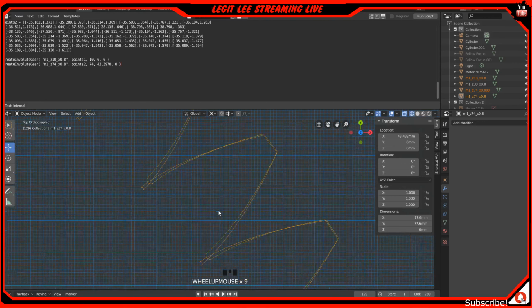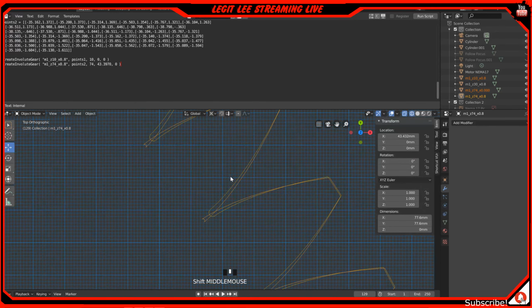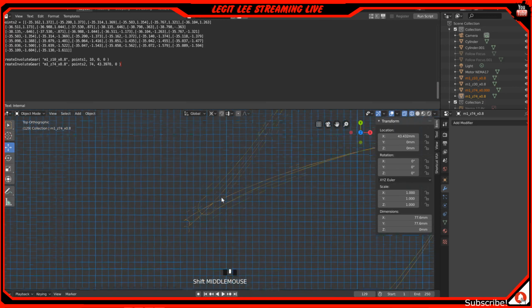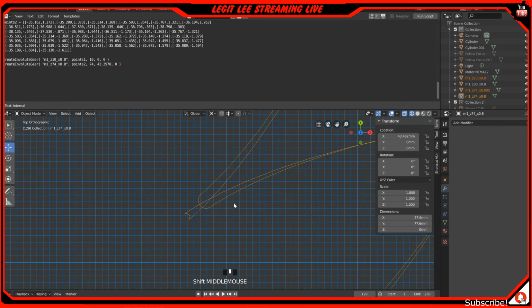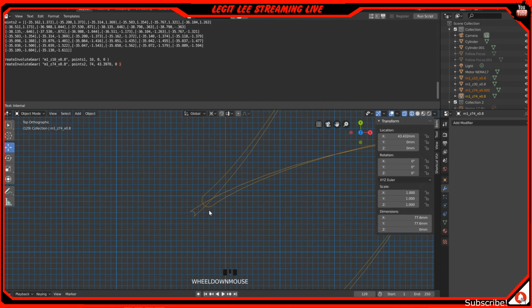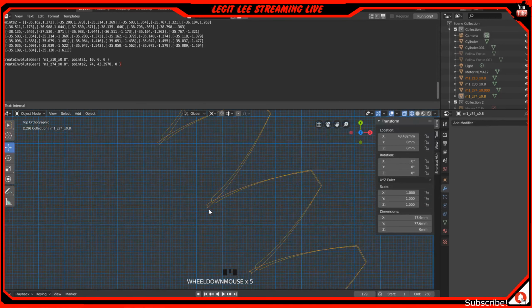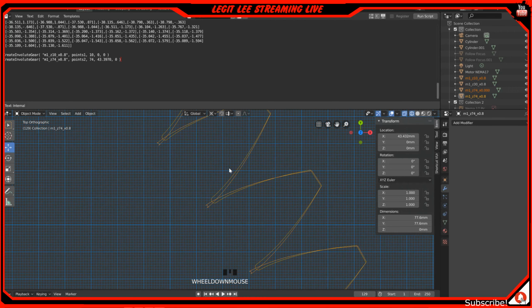So you can see the difference. Our pressure angle here on the second one has a little bit of a curve. So that's good. We needed more of a pressure angle, but that's not good enough. If we went down to 18, that gave us our curve instead of having this weird lump thing going on. We're going to have to add some more pressure angle. So I'm going to go down another 2. We'll do 16. See how that looks.